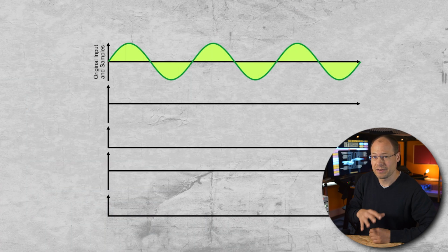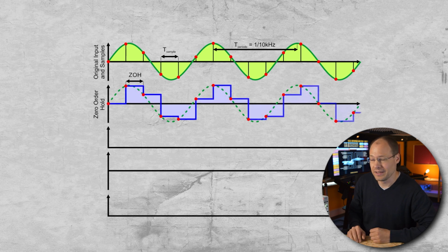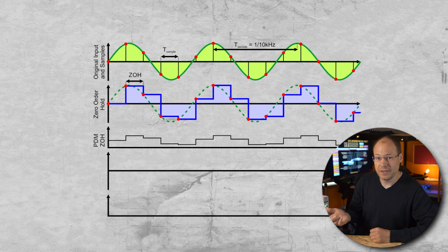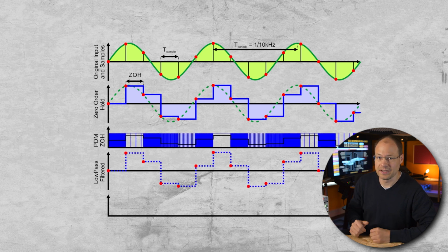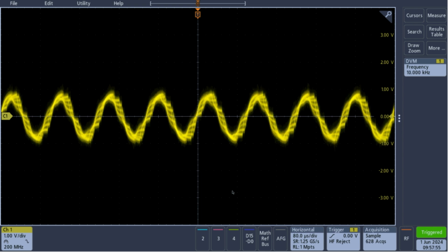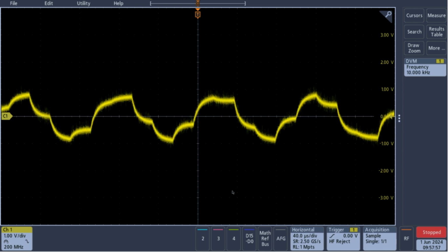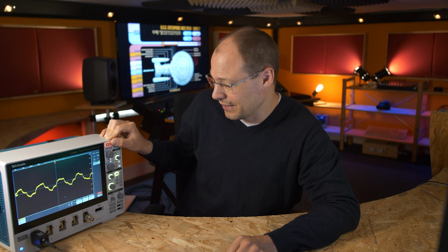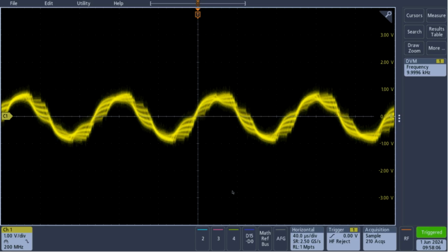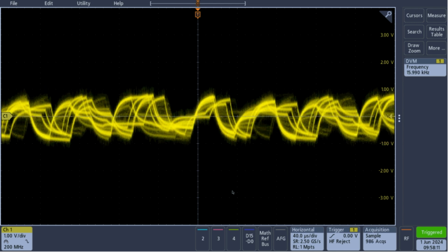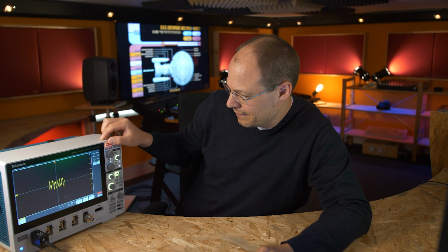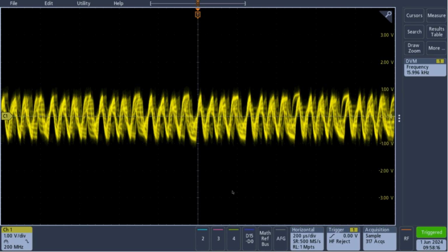And this is the problem with our zero order hold here in the FPGA, because we are getting new samples only every 20.8 microseconds at 48 kHz. And our PDM is working at 5 MHz. So our PDM is much faster than the samples getting in. So 10 kHz. Yep. This is hardly a sinusoidal waveform. And now even more, 16 kHz. This is more or less garbage.